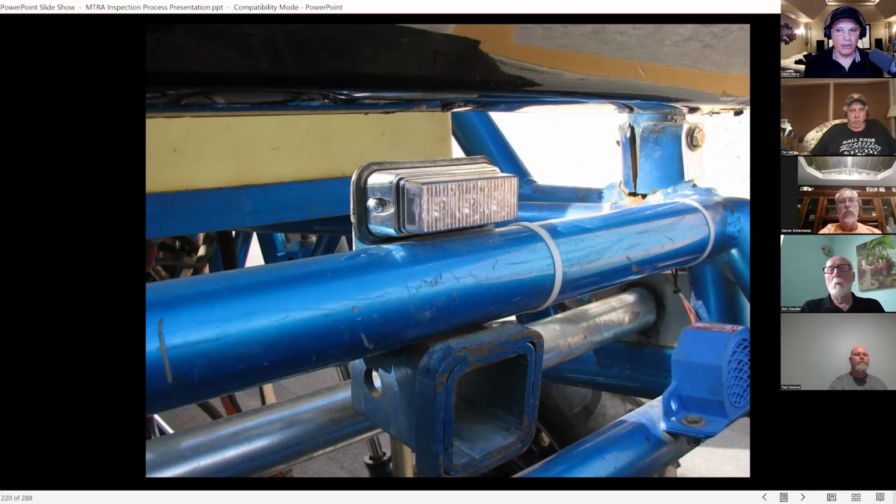The lights are important because, very often, like in the situation that we saw recently, when multiple trucks are running on the floor, sometimes you can't tell which is the one that's backing up. If you can't hear the backup alarm over all the engines running, at least you see that truck is in reverse. The light will catch your attention. It's more important than people give it credit for. Yep.